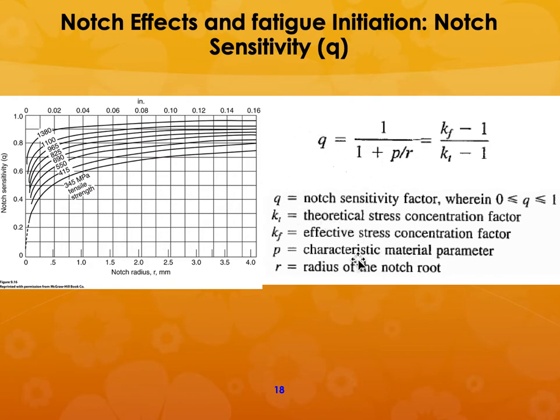So if you are given that value, and if you are given these curves, you should be able to calculate the effect of the stress concentration factor and the radius of the notch root. Then you can calculate the notch sensitivity factor or vice versa.